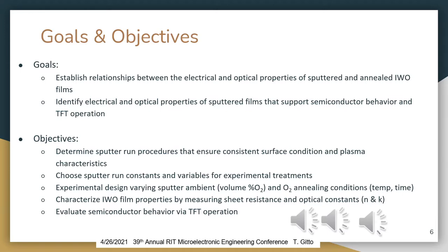Choose sputter run constants and variables for experimental treatment, experimental design, varying sputter ambient, and annealing with oxygen. Characterizing IWO film properties by measuring sheet resistance and optical constants, and evaluating the semiconductor behavior via TFTs.